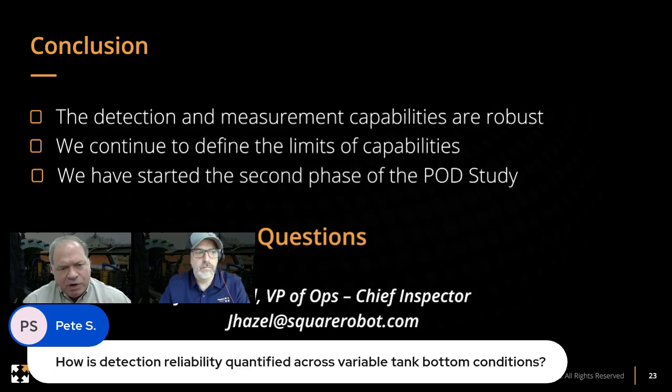But realistically, what we're looking at from a detection and reliability standpoint is how many multiples and what is the strength of the multiples that we're seeing across the sound path that we're measuring. As long as we are seeing good, strong multiples there, we have a high degree of confidence that we're going to be able to produce the right information for you.